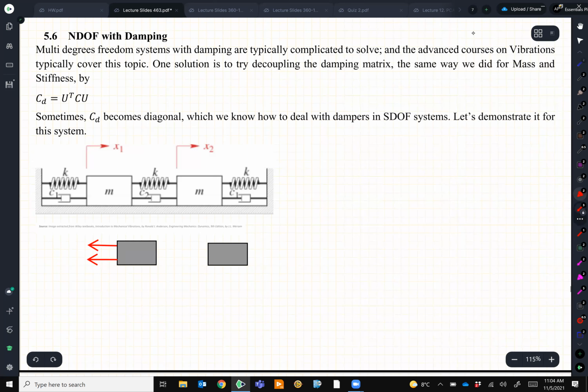I have the springs and damping over there, which simply this one will be Kx1. And for dampings, C1 x dot 1. One way to always check K and C: the forces are in the same direction when you draw the free body diagram, except for dampings, it is velocity.